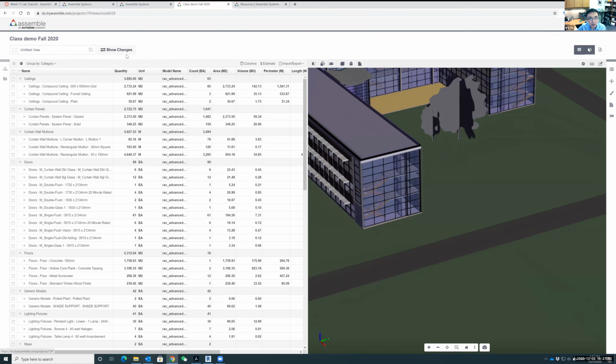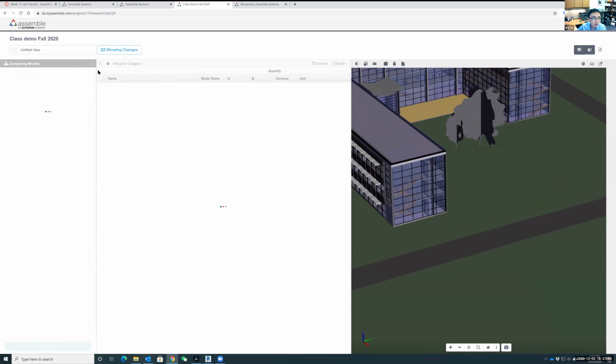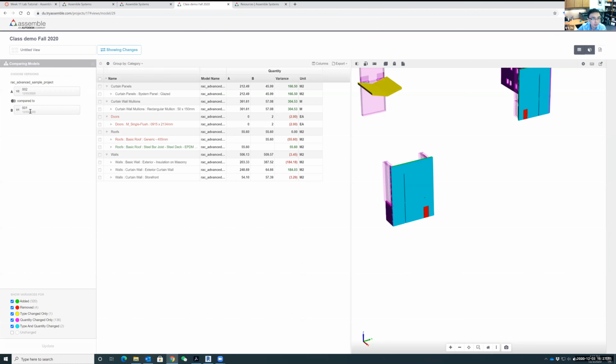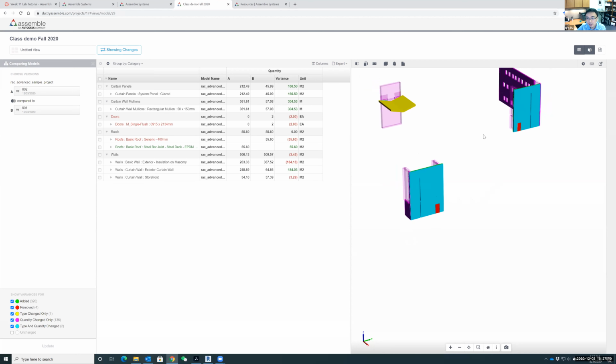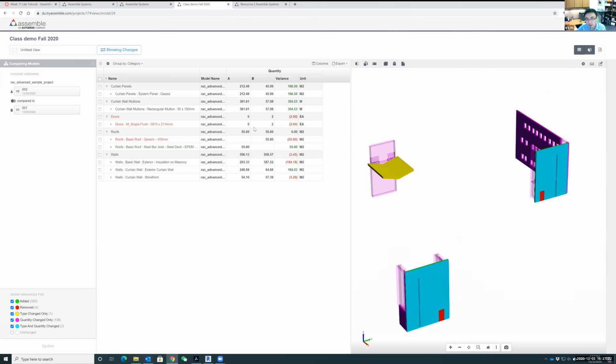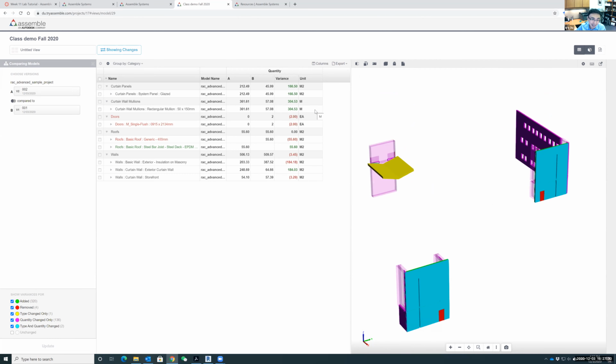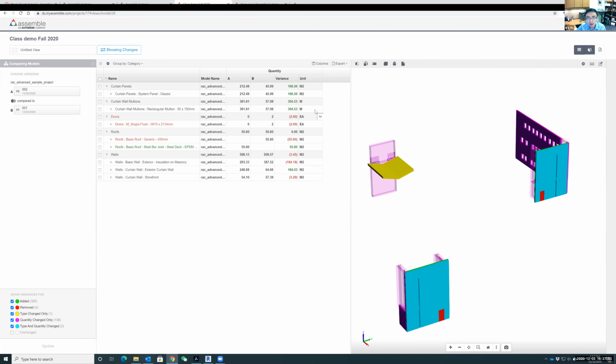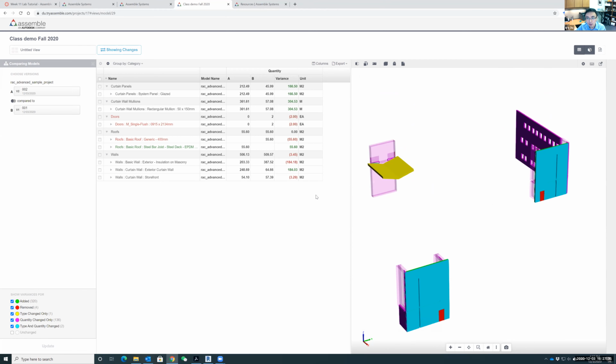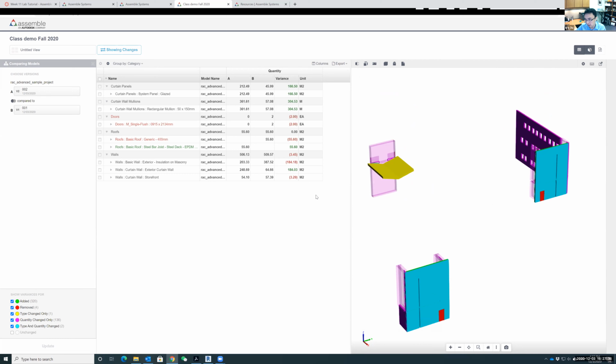But you probably notice that there's a button. It was grayed out, but now it's activated, called Show Changes. So let me click this button, and now it will show the 2 versions, version 1, version 2. And also automatically the color code: added, removed, type changed, quantity, everything. See, that's exactly what we changed in the model. And the magic is it also shows the quantity change. And if we create that unit price function in the database here, it will also show you the dollar change. Isn't this amazing?